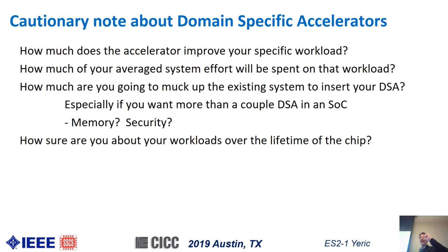But if you look at actually making a system, some SoC, and you're talking about putting 3-4 different accelerators on there, what you find is trying to integrate multiple accelerators onto a die, they start to conflict with each other. So putting a second accelerator dilutes the power of the first accelerator if they're having to use common security protocols, memory protocols, what have you.